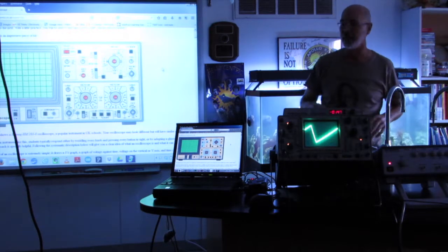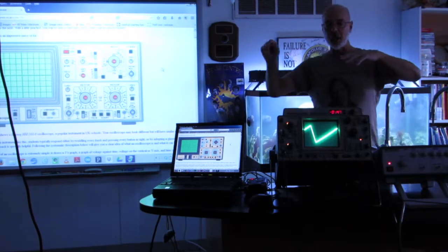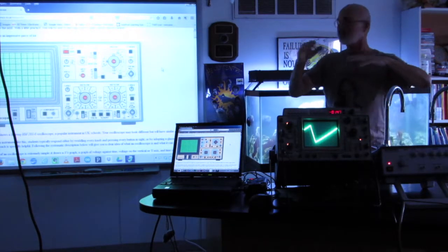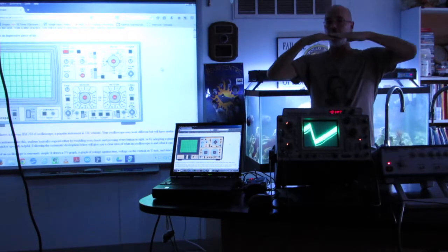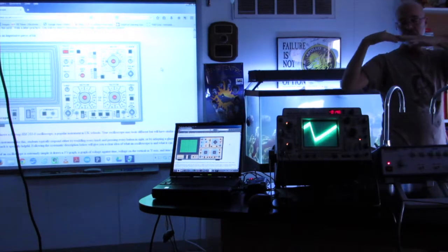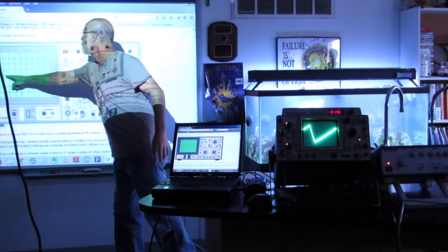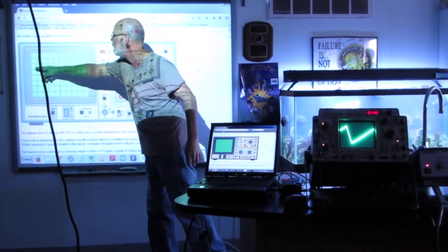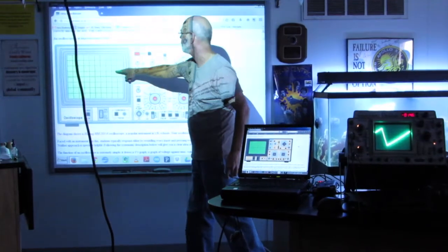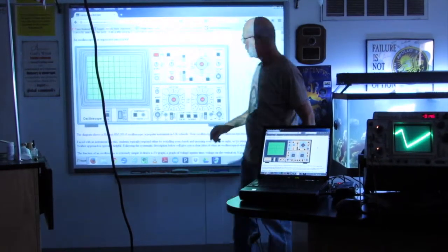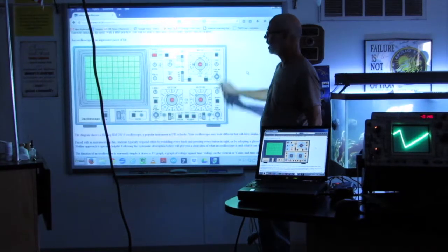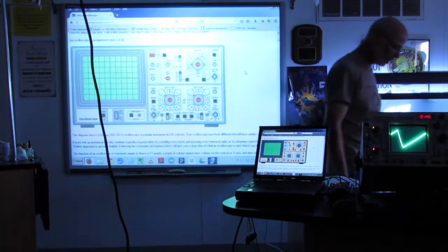Negative, it'll be a little lower. If I turn the trigger knob a little to the right from center, I'll be moving what's called the threshold level, the trigger level, to let's say 1 division. My reference point might be here, but I might set my trigger level to the first division above it just by turning the level knob a little to the right, to the positive side.